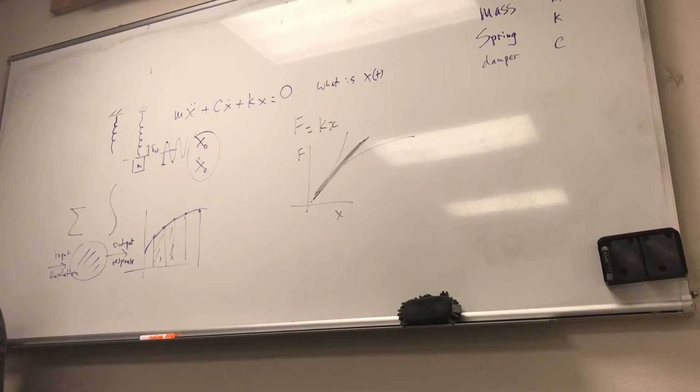Now, that doesn't mean that you can't take it even further, if you want to be crazy. All right, so this hopefully says that for a refined approximation, the weights of the frame and anvil and the foundation block are represented separately with a 2-degree of freedom model, right?